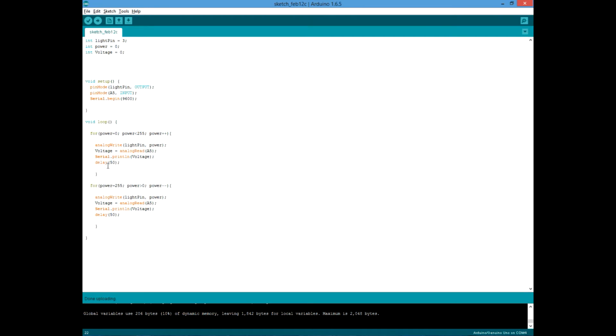And that's useful because these things run so fast that if we were to just not use a delay command and say go, it would get really confusing. And you'll see when we run this, the data starts streaming incredibly fast, and it's hard to keep up with. So we put a delay in programs sometimes to slow them down so that we can actually see what's going on.